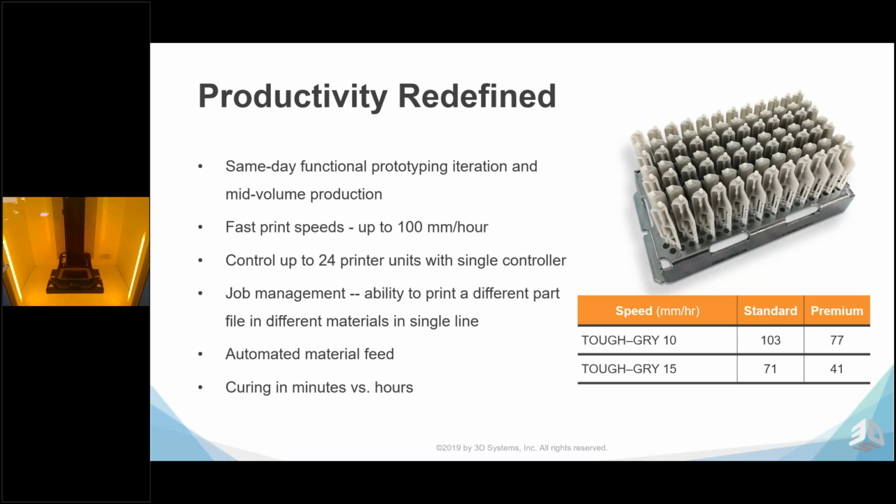So you start to think about some of the other technologies, like FDM, which is traditional 3D printing, where it has to trace all the geometry of the part, and if you add another part, it's just going to double your cycle time. But here, if I have one, or however many are here, about 100, it's all going to take the same amount of time. Because if we think about the light again, the light is curing the whole layer all at the same time, no matter if it's one part or 100.